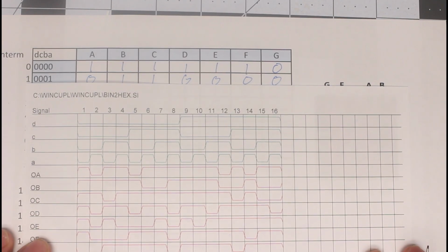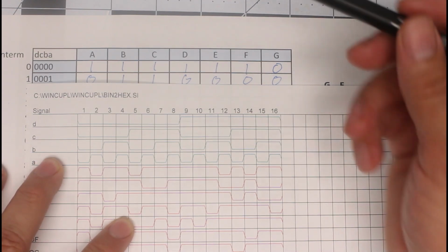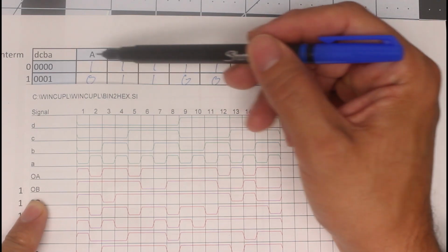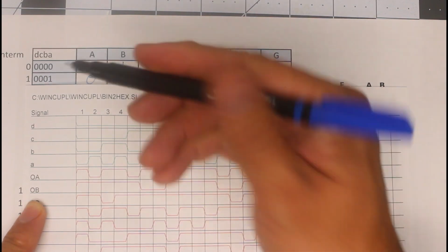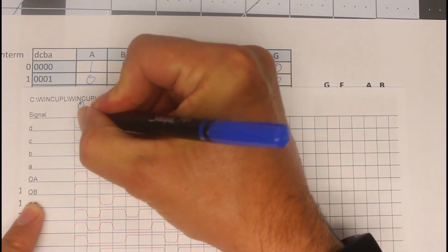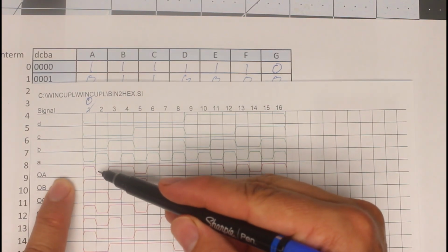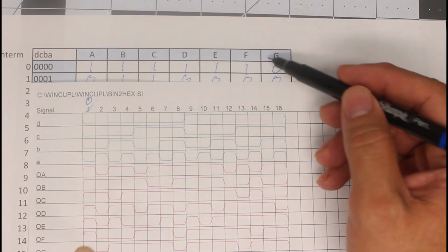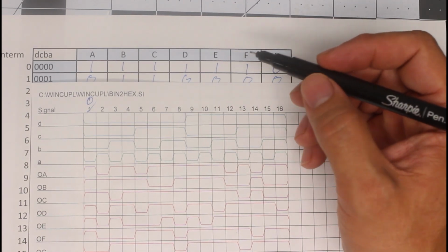We'll take a printed copy of the simulation output and do a quick comparison just to show that we did indeed get our programming right. So let's go ahead with the first number, 0. And in this case, the row will be matched up to the column. So this will be the row for address 0. And we can see that, in fact, A, B, C, D, E, F are all high, and G is low. So our input for 0 worked.